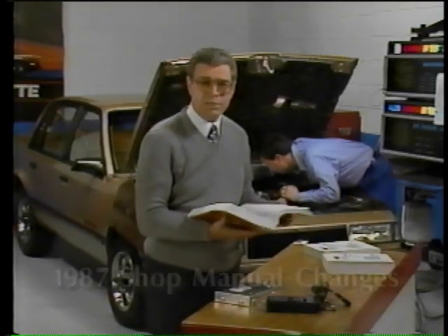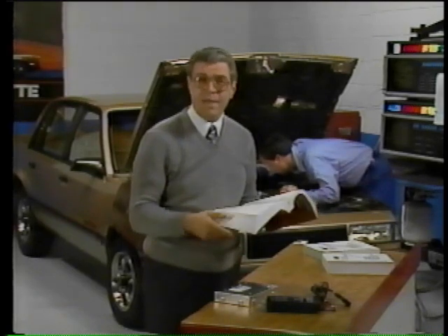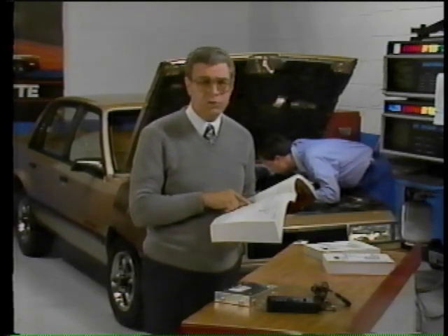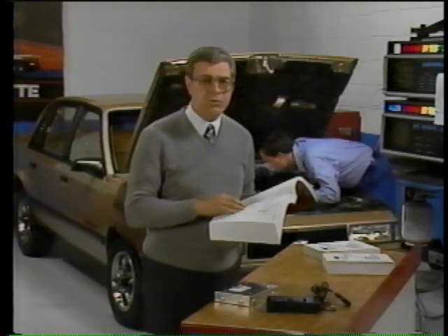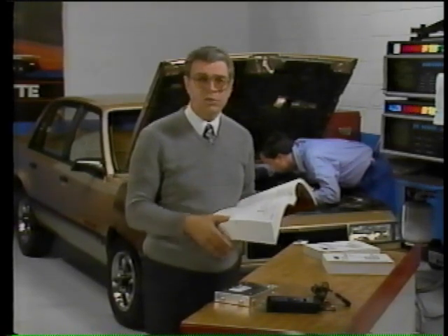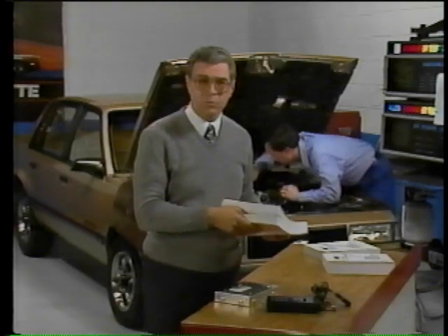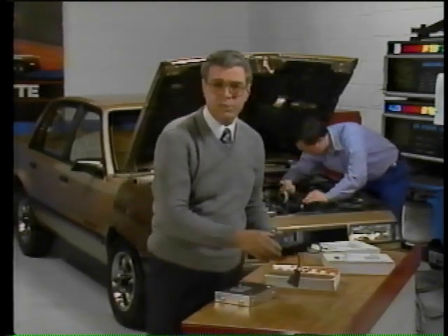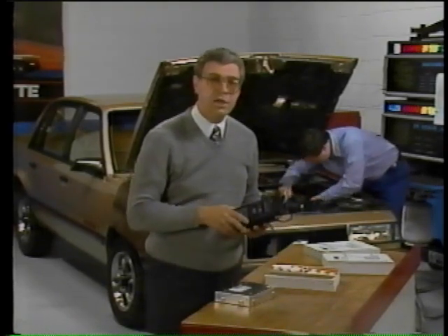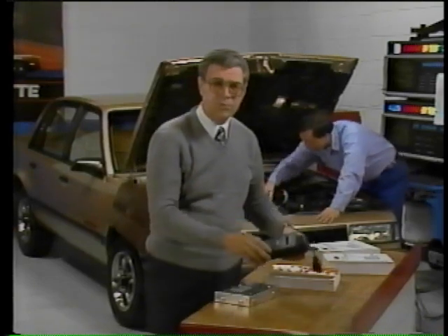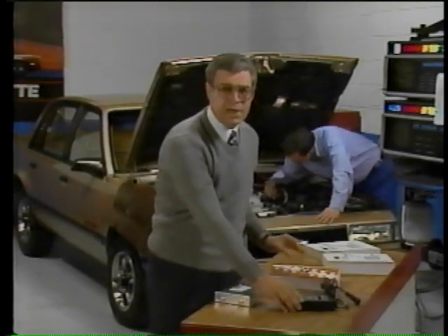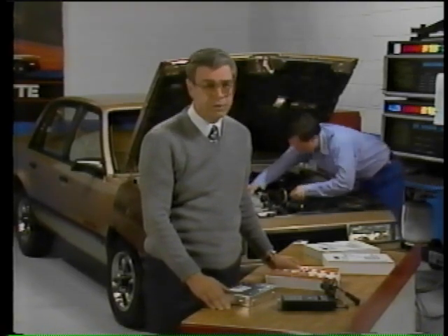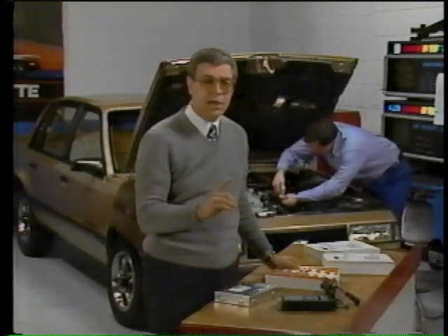Due to the changes in the computer command control system and in the scan tools, the 1987 shop manual uses scan tool steps exclusively in many of the trouble code charts, so you'll need a scan tool to diagnose these trouble codes. Using a scan tool markedly reduces diagnostic time and improves your diagnostic accuracy. Now, before we use these trouble code charts, keep in mind the same engine in a different body style vehicle can have different equipment, and this can affect diagnosis.